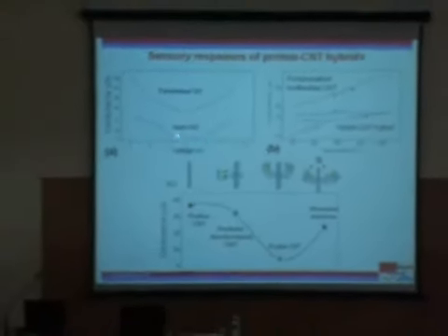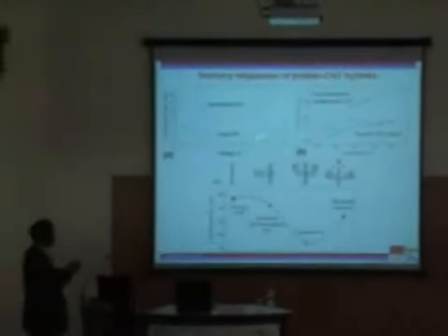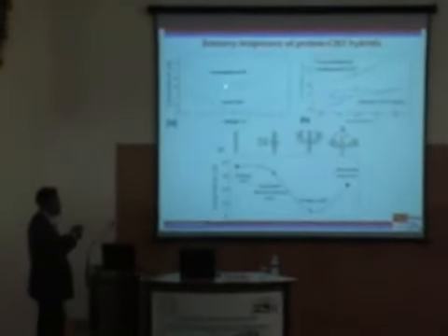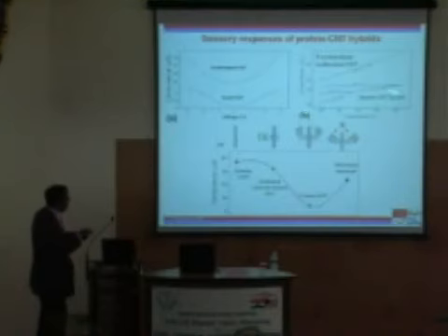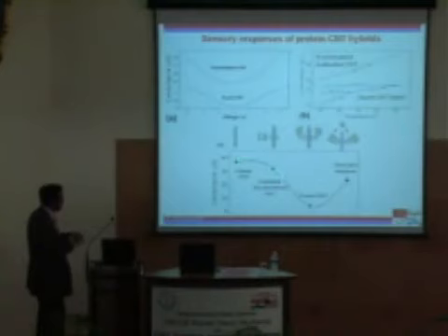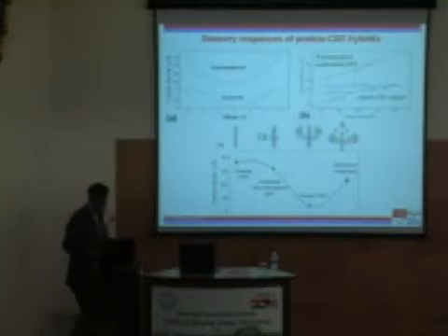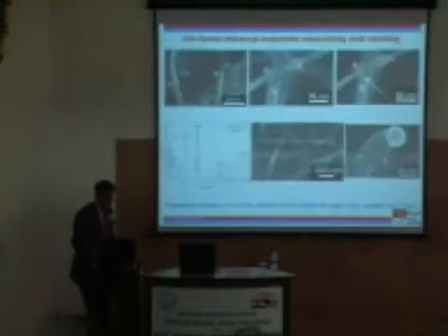Now, just to show you that you can indeed do this, you can see that the azurin derivatized nanotubes show the IV characteristics that are like this. Functionalized tubes show these, and suppose I expose them to thermal stresses, then the hybrids actually show irreversible behavior, while the functionalized tubes show a reversible behavior. So, I can see that the changes in the conductance actually are quite large. Okay, so you can use these as different states if you can design architectures appropriately.